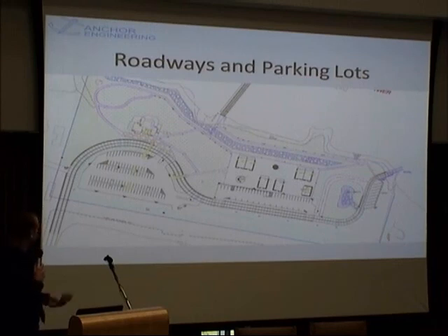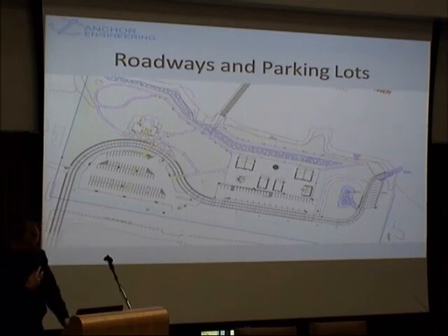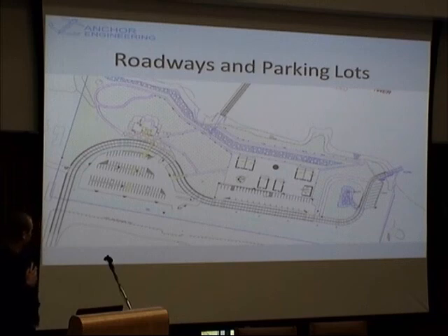It was designed to Rhode Island Department of Transportation standards with a design speed of 25 miles per hour. The grade at the entrance is pretty steep, and it eventually, as Chris talked about, flattens out into the existing grade. The asphalt we used was recycled because it'd be cheaper and easier to construct.